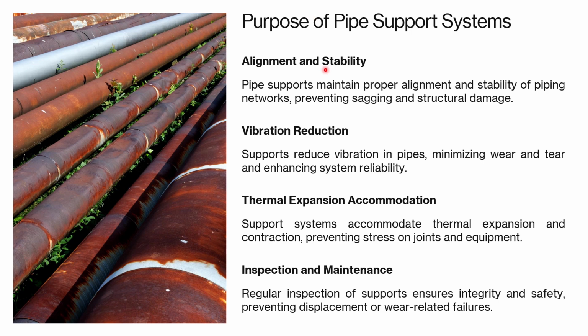Okay. So how do you ensure that supports are installed accordingly? We have design specifications, and based on those design specifications, and it varies from pipe size to pipe size, what type of support and how much distance there will be between the two supports. And then they are inspected regularly for wear and displacement. It's not the case that you provide a support and after that you don't even see it for 20 years. It's not the case. Maybe in routine maintenance you will check whether the supports are capable of taking the pipe load, whether there is any wear and tear or not. So this is a proactive approach, guys, and it helps in maintaining system integrity and operational safety.